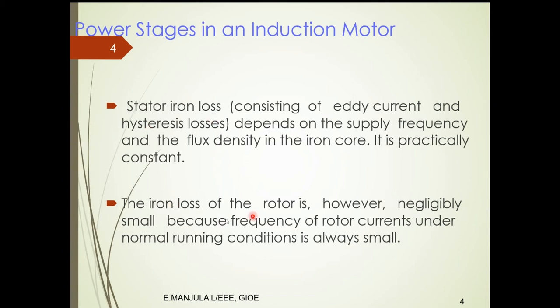The iron losses in the rotor are, however, negligibly small because the frequency of the rotor currents under normal running condition is always small. In running conditions, the frequency of the rotor is f dash equals s into f, which will be a small quantity. The frequency will be like 2 hertz or 3 hertz. So the iron losses in the rotor at running conditions are negligible.